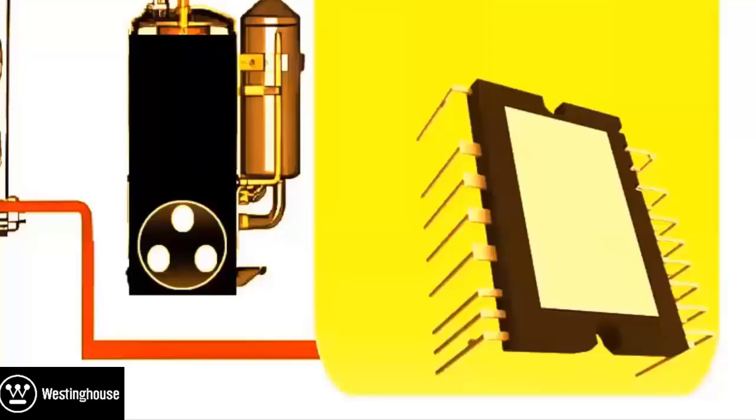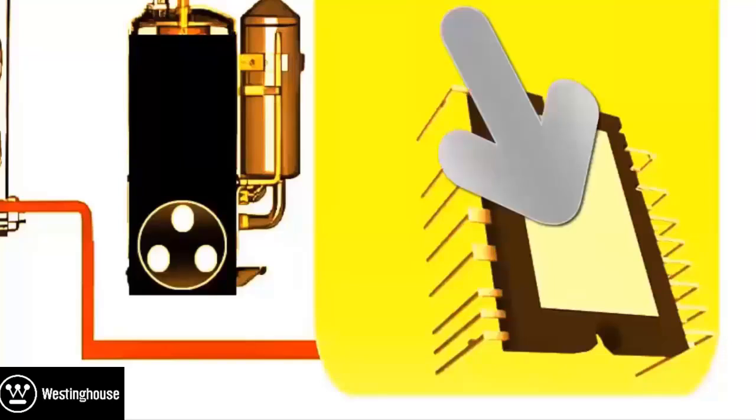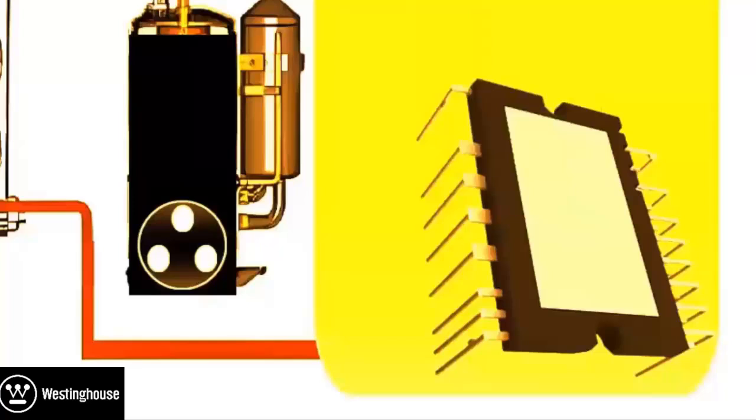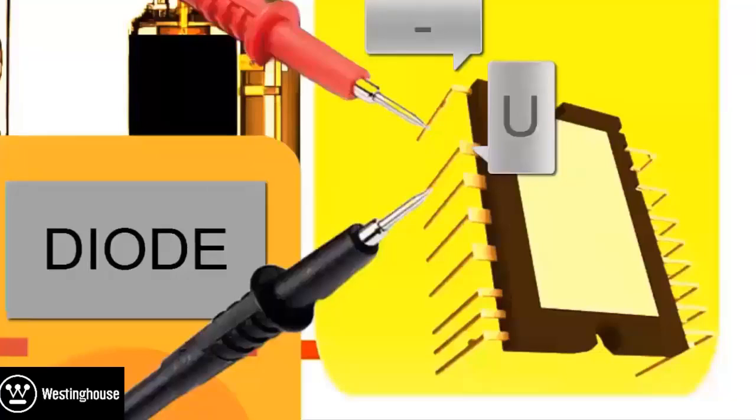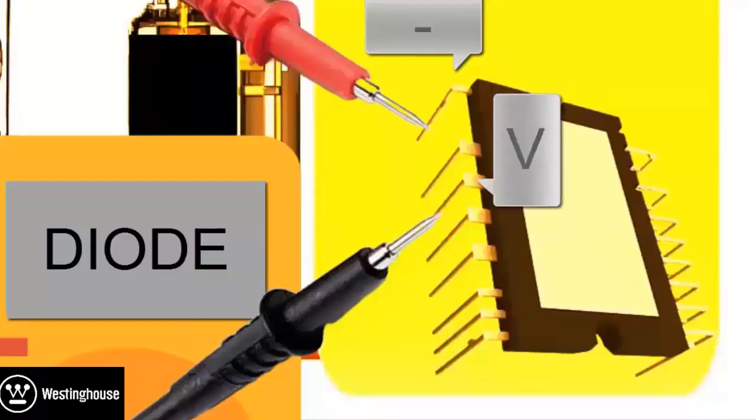2. Turn off the power supply to the electronic board. 3. Wait a few minutes to allow the electrolytic capacitors to fully discharge. 4. Identify the module's pins. Use the serial number of the module to identify each of its pins. 5. Perform necessary measurements. First measurement.